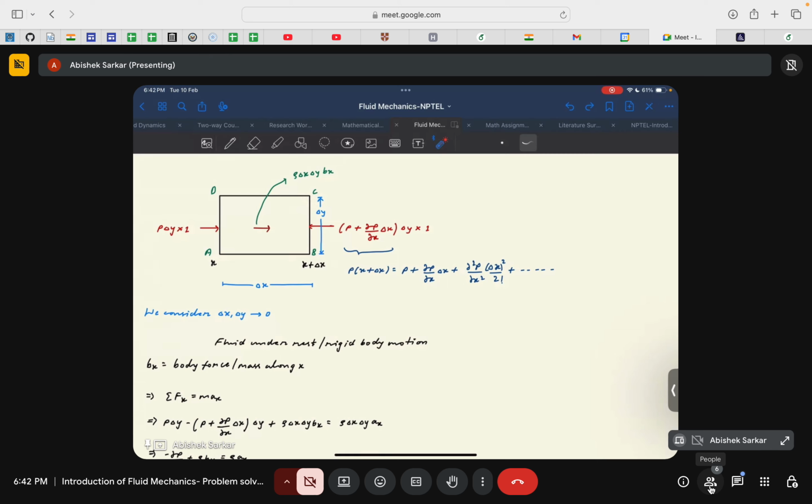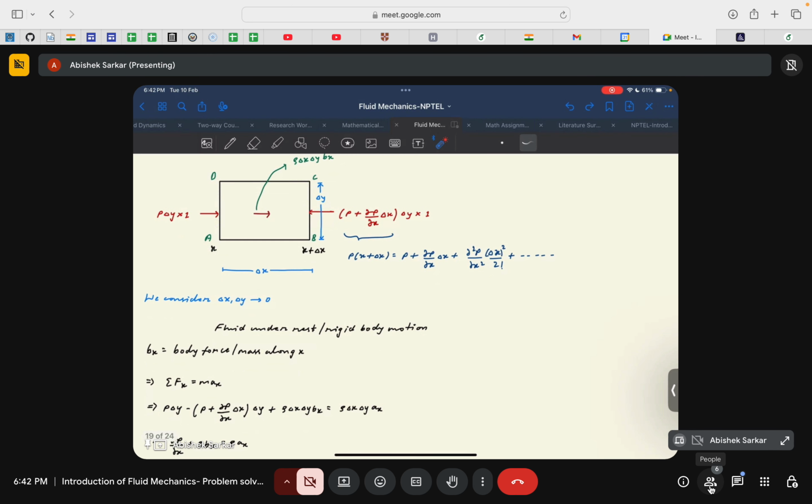As I mentioned, the forces acting are the pressure forces and the gravity, or body forces. Other forces that arise from shear will not be considered because of the fluid statics approximation. Now, we will just consider force balance along the x direction for simplicity. On the surface AD we will have the pressure force as P times the area, which is delta y times 1. So the pressure force is P times delta y times 1, or if you disregard the 1, P times delta y.